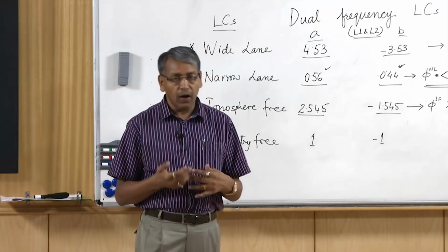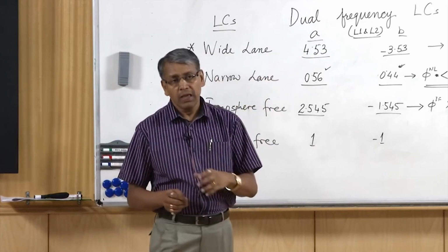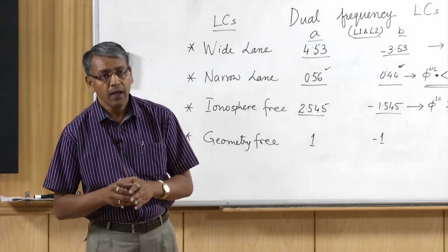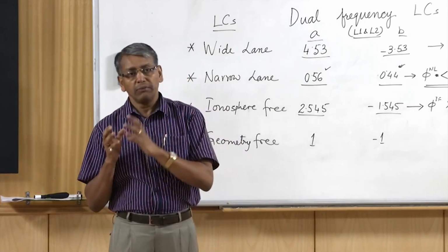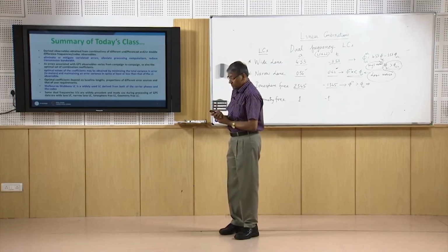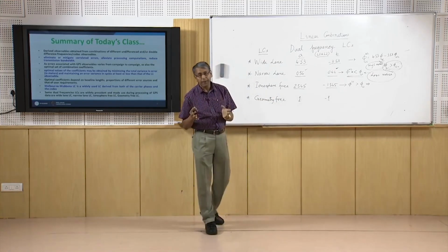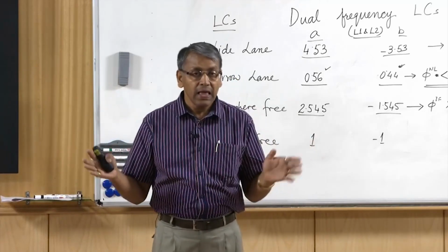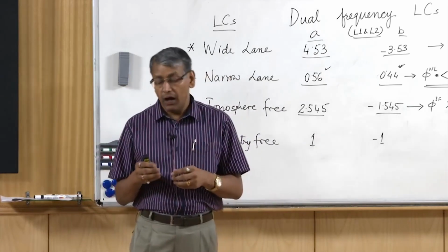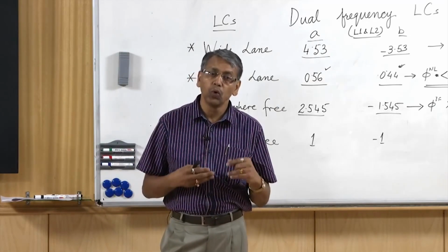However, to make it optimal we should see that the errors in the combined signal are less than what is available in a single L1 signal, and the optimal values of the constants A, B, C will depend upon the baseline length, the amount of different types of error and their mutual dependence in the observables, and the amount of accuracy we look for.